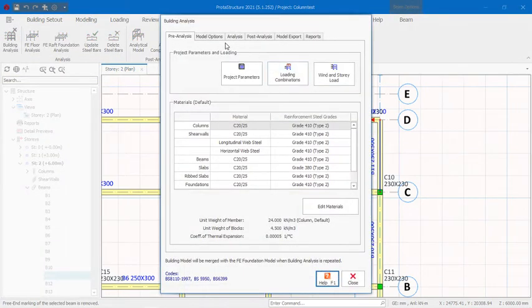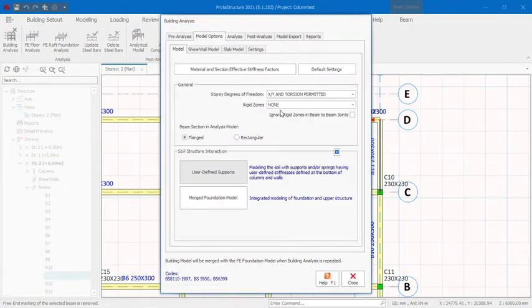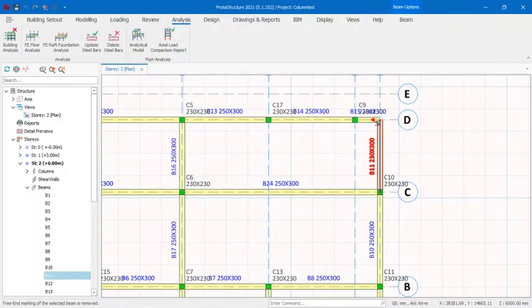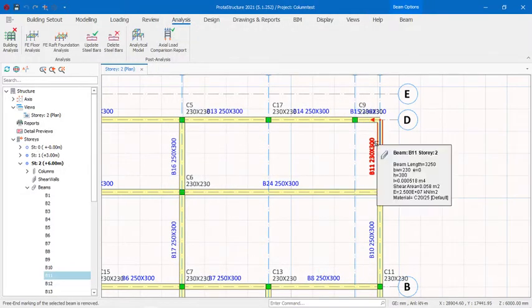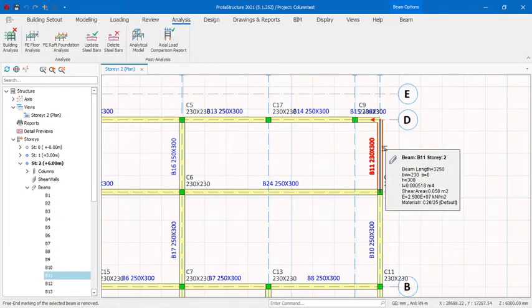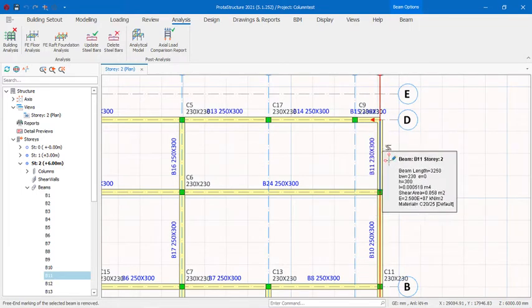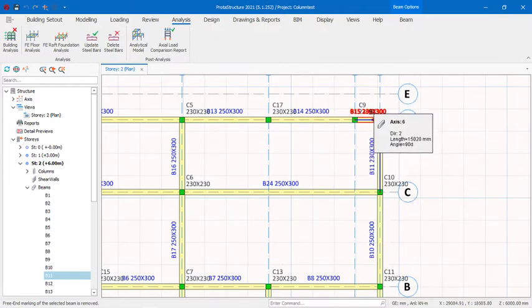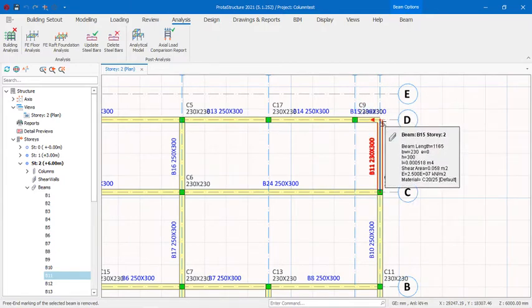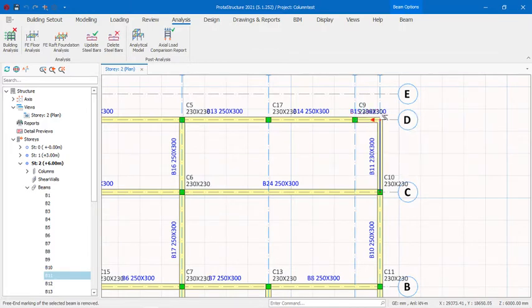So whether or not you define a point load depends on the case you want to assume. If I am assuming that half of this beam will be acting as point load on this particular beam 15, then I know that if I idealize this, I will have a straight line whereby I will now have point load at the end of it.